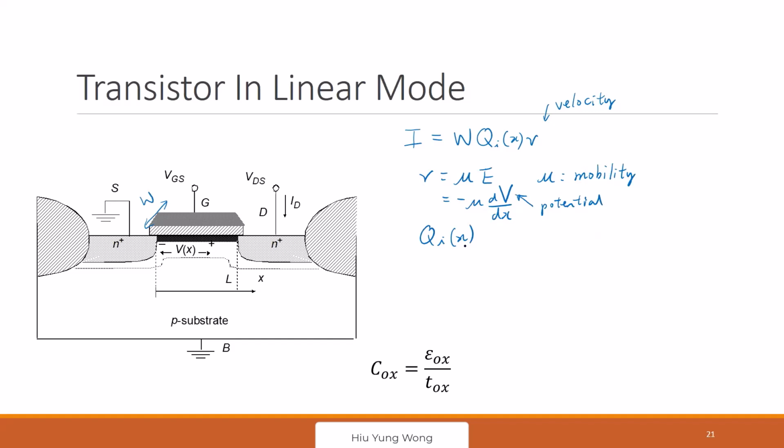It may be confusing, but just go through what we have discussed. All the gate is doing is inducing the charge under it through capacitive coupling. So isn't this nothing but just C times V? Correct? Charge equals C times delta V. What is the capacitance in our case? Oxide capacitance. Very good. It's just the oxide capacitance, right? This is the T-ox, and it is given here.